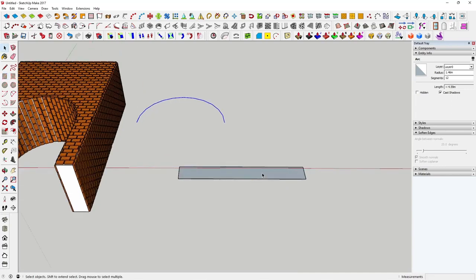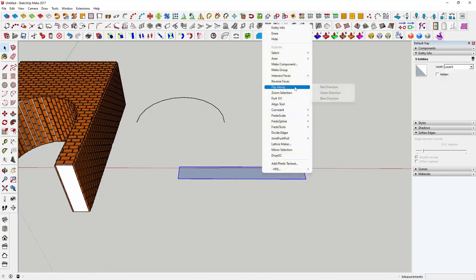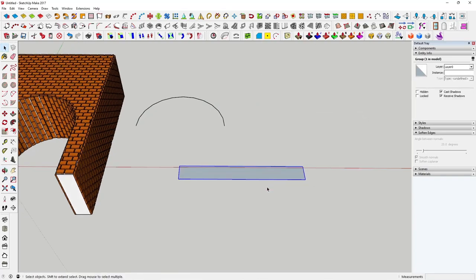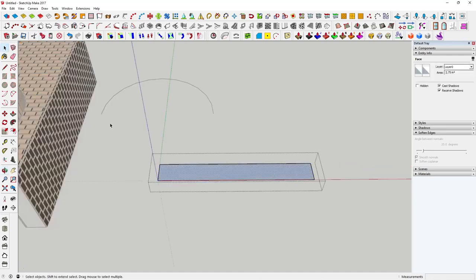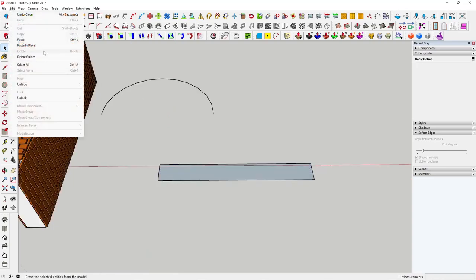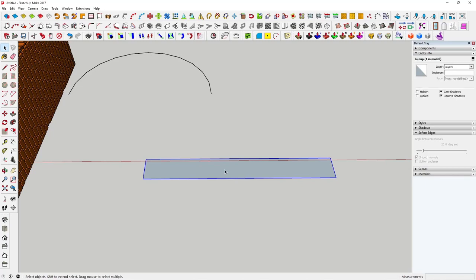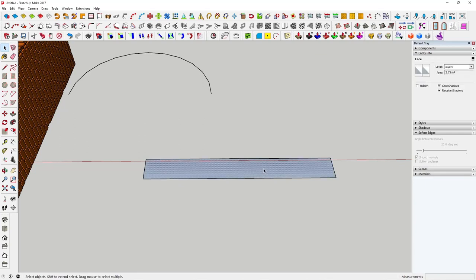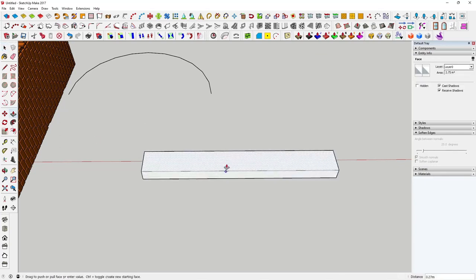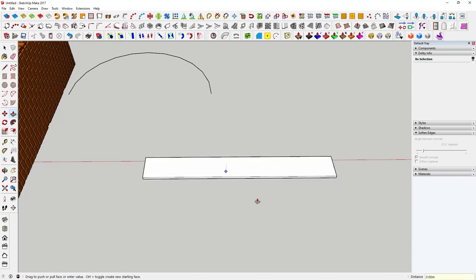And we're using this pick tool, double click, right click, make a group. We're using this as a guide. Copy the face, edit, paste in place. Sometimes it won't pick the front, it picks the underneath. So if we pick the underneath, we can hide it for now. And we're left with the front. We'll pull it up 0.06, because when you add your bricks, you're up to 1mm, which is a good size for bending and stuff.